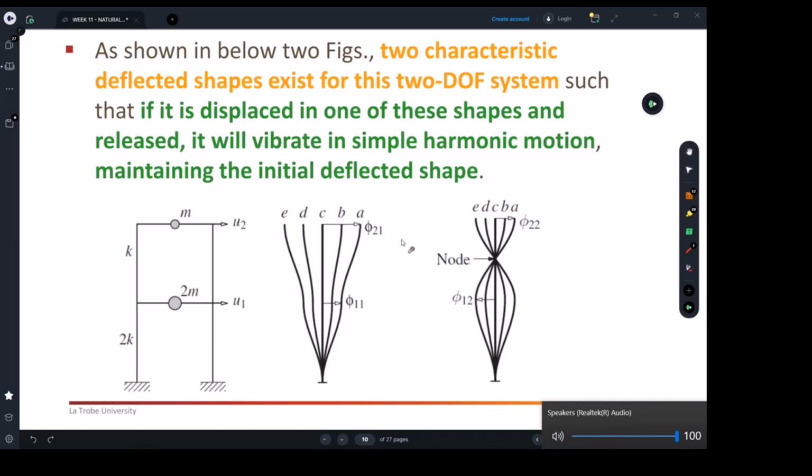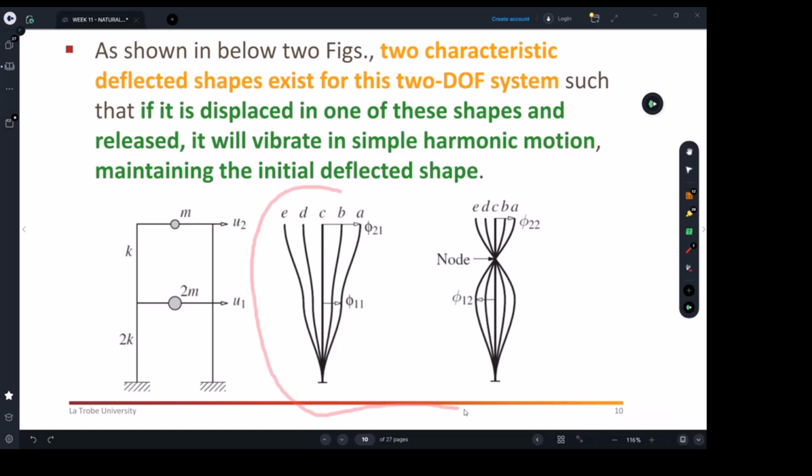And as you know, we need to know the time period and the frequency, because after you know it, you can compare it with the forcing frequency. And if they are matching, that's a problem. You're going to have a resonance problem. Then we have to change something with the building that will keep the natural frequency of the building away from the forcing frequency, whether from earthquake or wind or whatever it was, and then get things to be more stable and static, or with limited vibration.